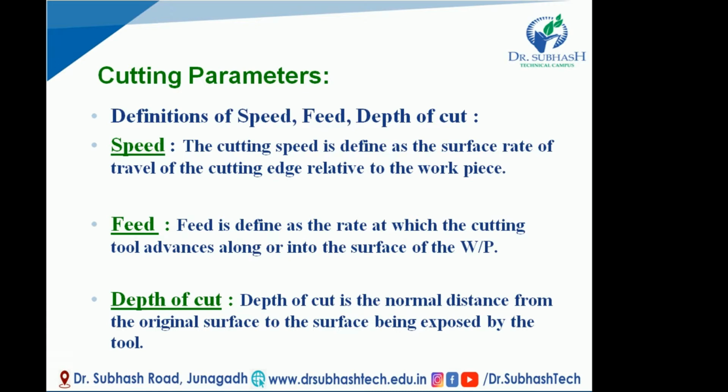So how can we define speed and feed? Speed is defined as the surface rate of travel of the cutting edge of the tool relative to the workpiece. And feed is defined as the rate at which the cutting tool advances along or into the surface of the workpiece.